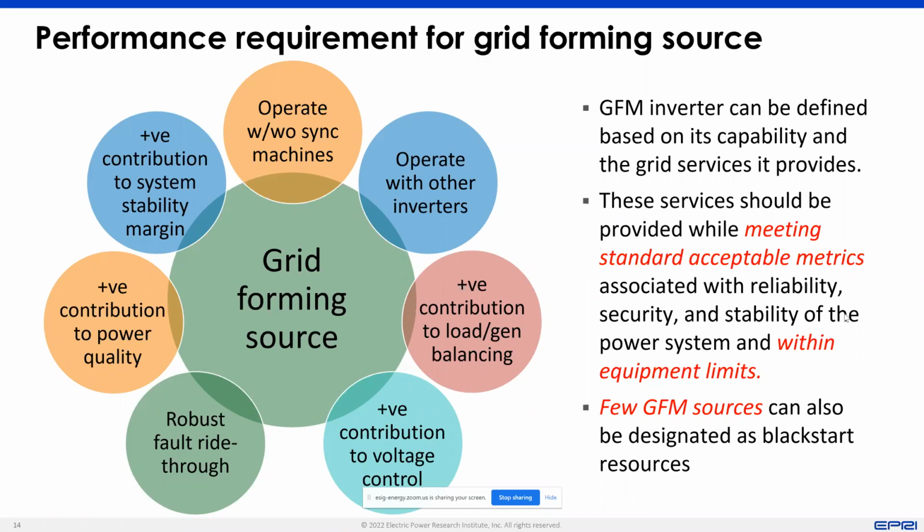And what that will do is help bring in grid forming technology maybe faster to the system, because black start capability, being able to provide inrush currents, being able to provide motor starting currents, being able to take care of faults in that environment where the system is extremely weak, is still not well known for inverter resources.